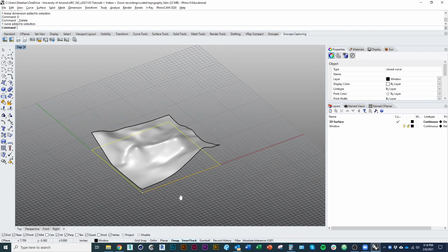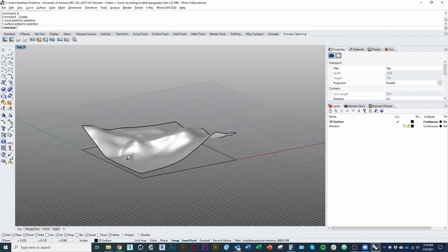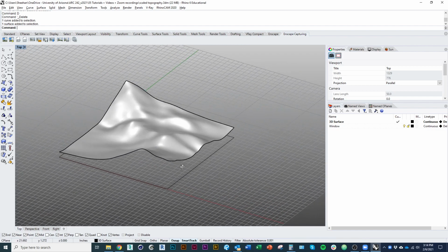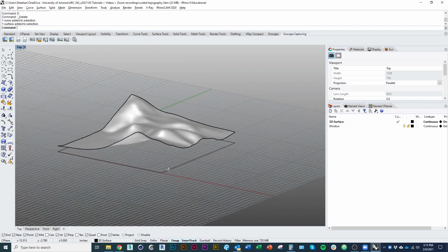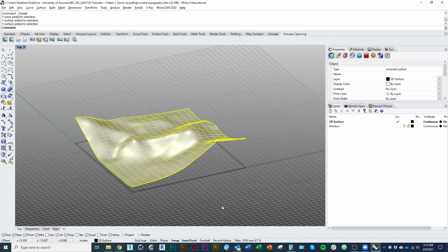Now, one thing that's going to make this a whole lot easier: we're going to make contours through the surface like we did at the end of the last video, but we want to first make it into a solid. When you make a topography model this way, you're basically going to stack up pieces that are cut out to be the size of the contour, but we're also going to have a base, right? So we need to figure out what's the thickness of the base between the lowest point and the bottom of my model, what's the step size for each layer, and then what are the extents in this direction, right? Because if we were to contour it now, we would just get one line that goes through that surface.